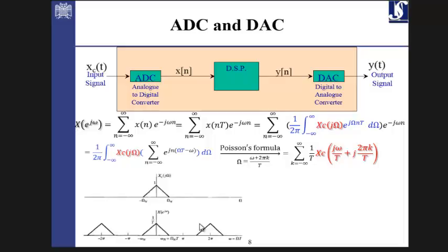So in actual terms, it means that if your signal in the continuous time domain, x of t, has a continuous time Fourier transform like this, which is band limited, so it's active from minus omega n to omega n, that's the omega of CTFT, not the omega for DTFT, and it looks like this, then passing through the A to D converter, what is the result?